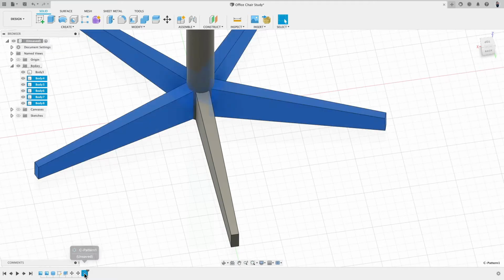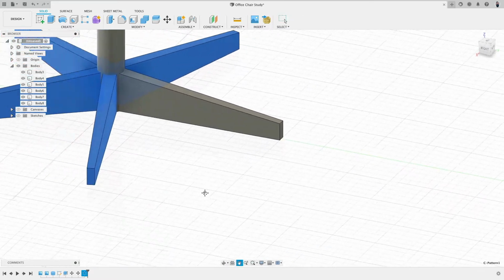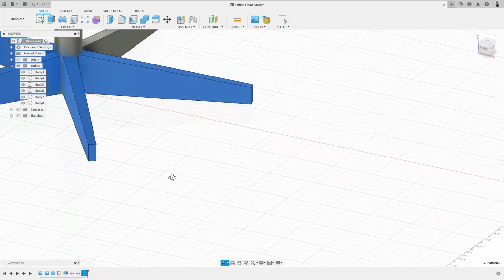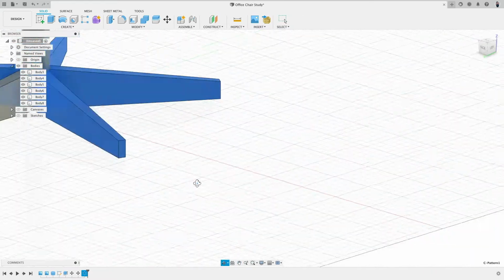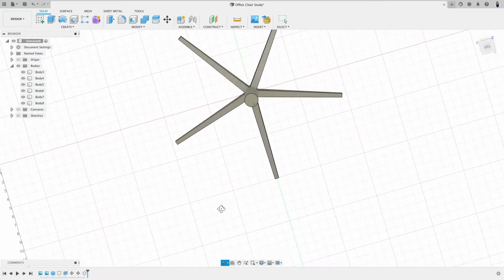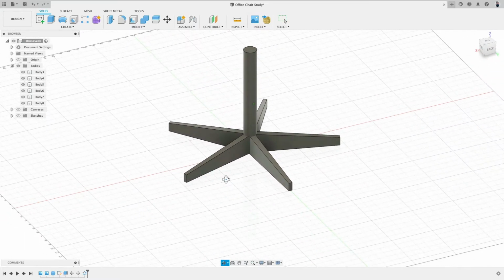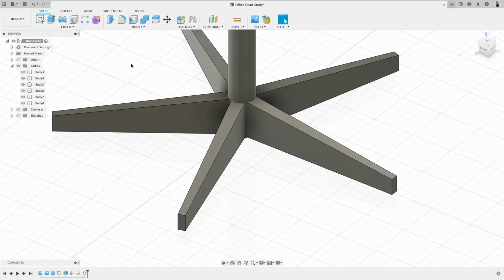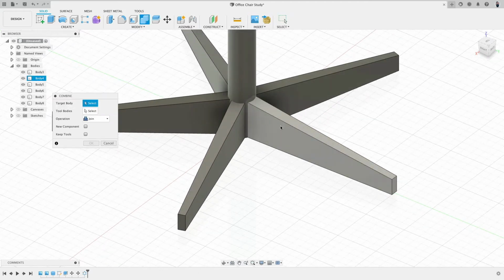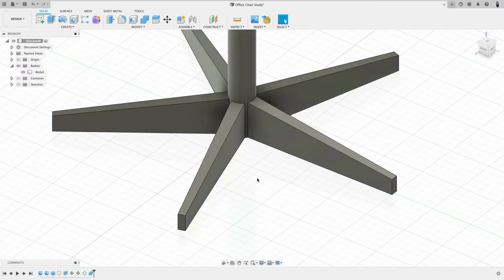And because this command makes a circular array of the body, basically you see how all the changes I put before the circular pattern command are in there now. Very nice. Okay, good. So this might actually look pretty fine. I will do a combine and say, hey, all you here combine. Very good.